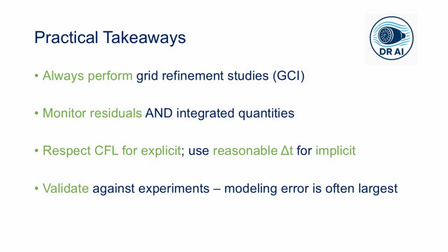Now, here are the final concluding remarks. Always perform a grid refinement study. It is your best defense against discretization error. Monitor the residuals and the integrated forces. Do not rely on the residuals alone, and respect the CFL condition for explicit schemes. For implicit, still use a reasonable CFL to maintain temporal accuracy. And when we validate against experiments, modeling error is often larger than numerical error.